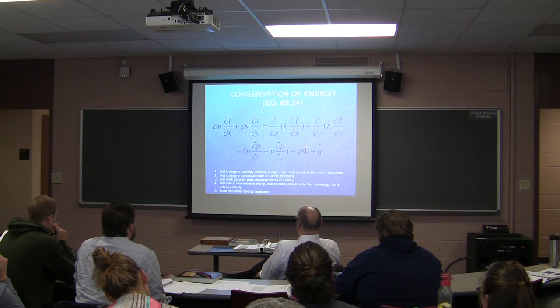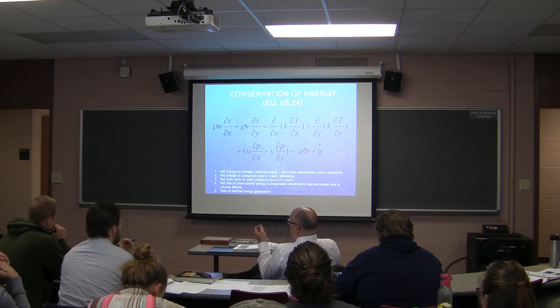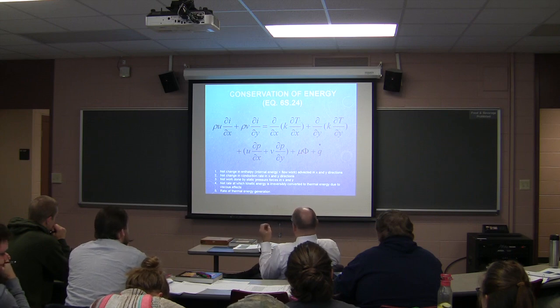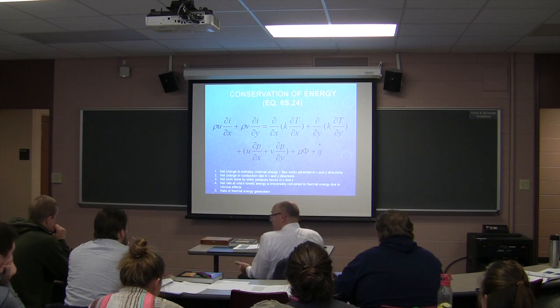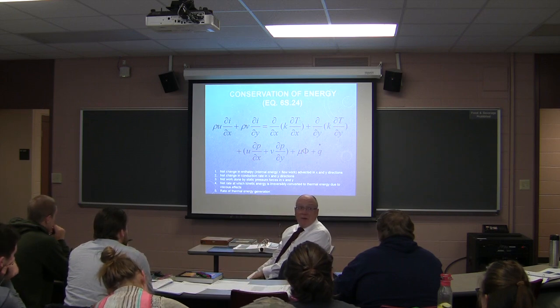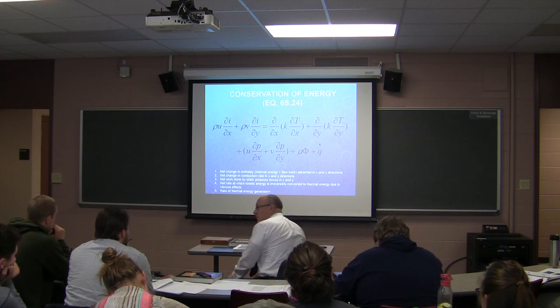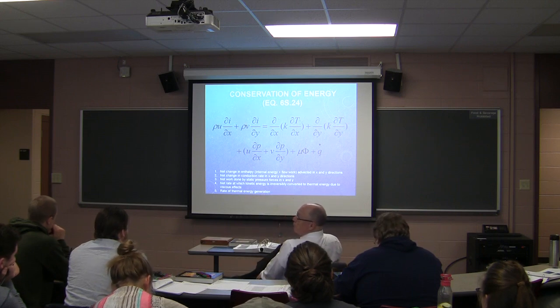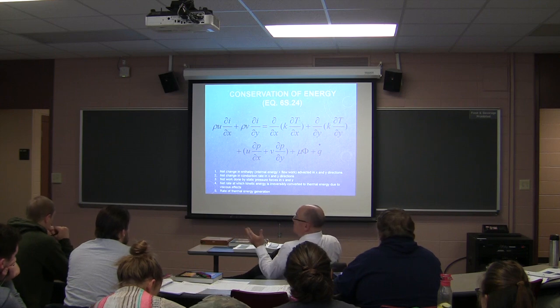And by the way, what is viscous dissipation? It is the net rate at which the kinetic energy is irreversibly converted to thermal energy due to viscous effects. What is that? You've had fluids. It's the frictional pressure drop, okay? Associated with a real viscous fluid flowing in a real channel, okay?